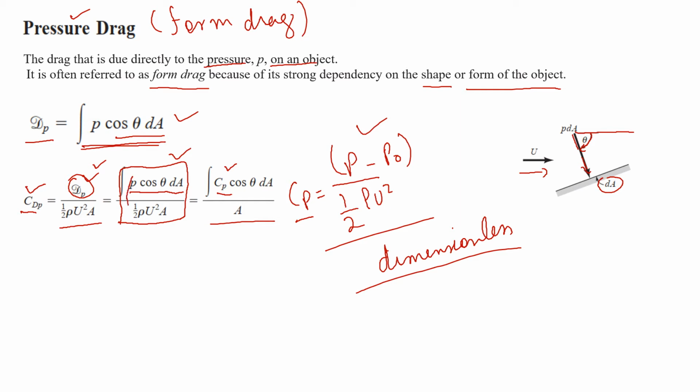Here again the pressure coefficient is equal to this term. As you can see, if we take out these terms right here, we can write them in terms of the pressure coefficient. If we take a certain reference pressure, for example, if the reference pressure is a vacuum, then this pressure will be equal to 0. We will get P divided by half rho u square, and if this is some amount of pressure, then we will be talking about gauge pressure that will be subtracted from this pressure, and we will take the actual amount of our gauge pressure. So in both cases we will be left with this term right here if we know our reference pressure. That term right here is equal to the pressure coefficient.